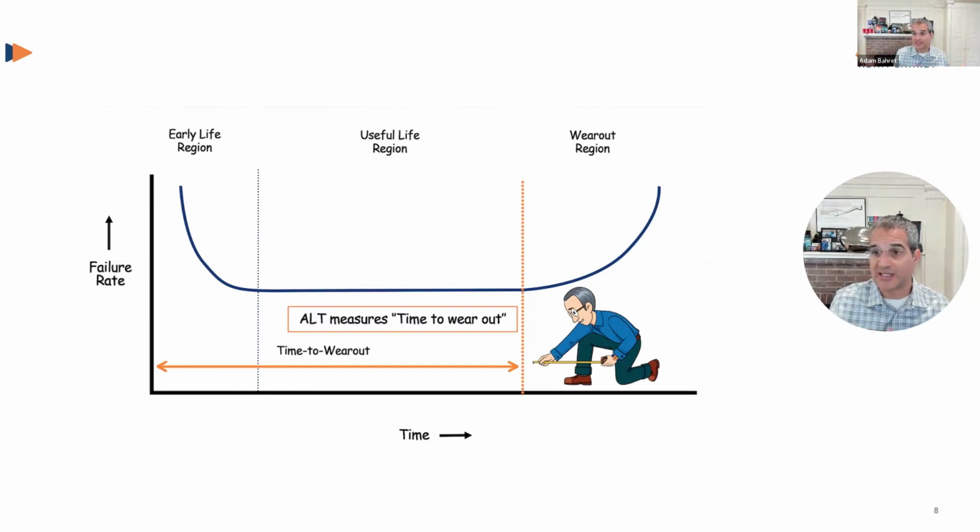In the one with dry rot, it might be at super high altitude where ozone is higher, and it might be a tire that doesn't get used as often, right? That's why they put years and miles in the warranty. Whereas the one that wears down first would be one that did a lot of mileage.